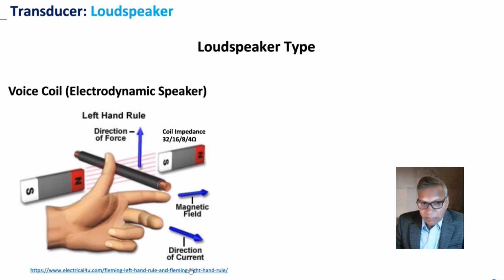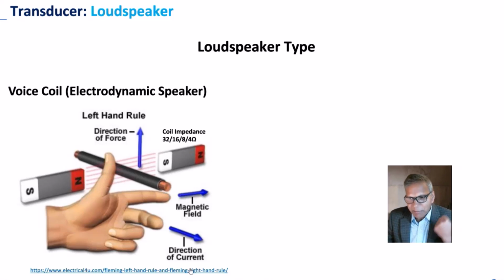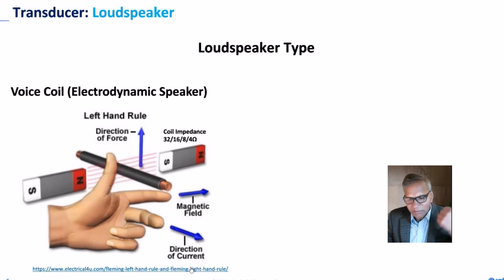One of the limitations of the voice coil-based is, A, it consumes power, and it requires a magnet, which means these are bulky. On a wearable form factor, specifically for a smartwatch, to generate a loud sound, we need either a larger loudspeaker or a deep cavity. We don't have that, both in terms of the space and